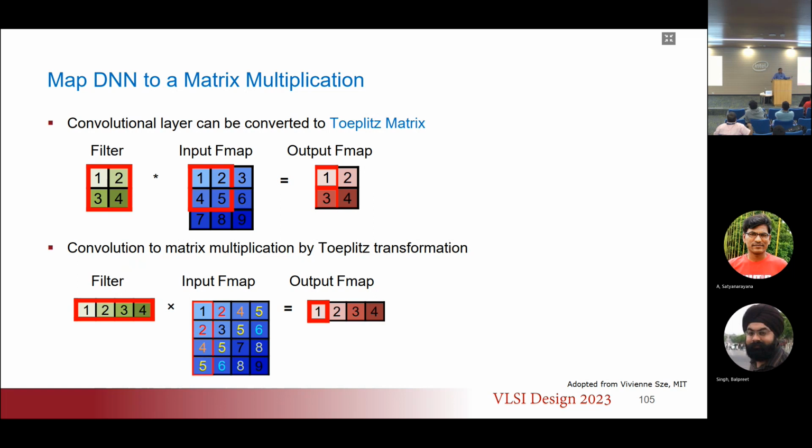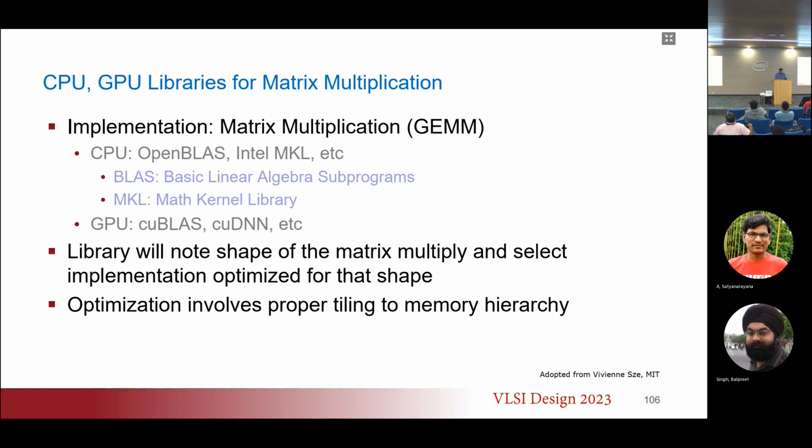If I didn't do the data layout, then in my regular hardware accelerator, I'm not going to have a smooth flow like this way or that way. I'll have to go like this, and that would not be the best way to design. So basically, I have to do input processing on the data such that the data aligns correctly. And the second thing I want to do is reuse the data in my accelerator as much as possible.